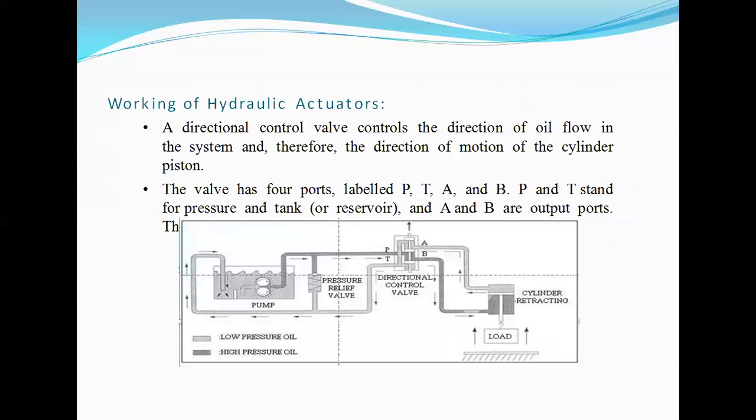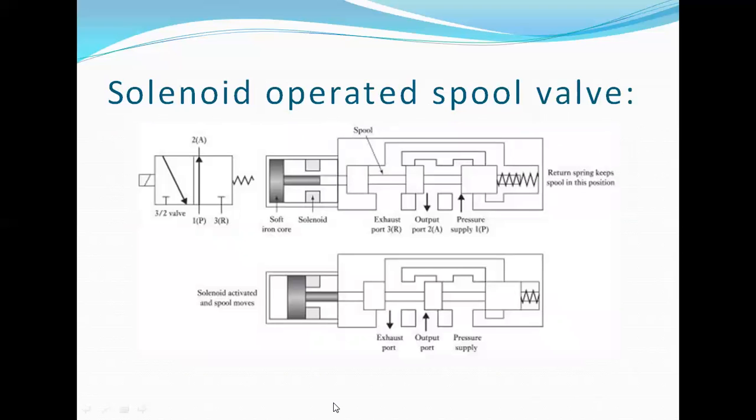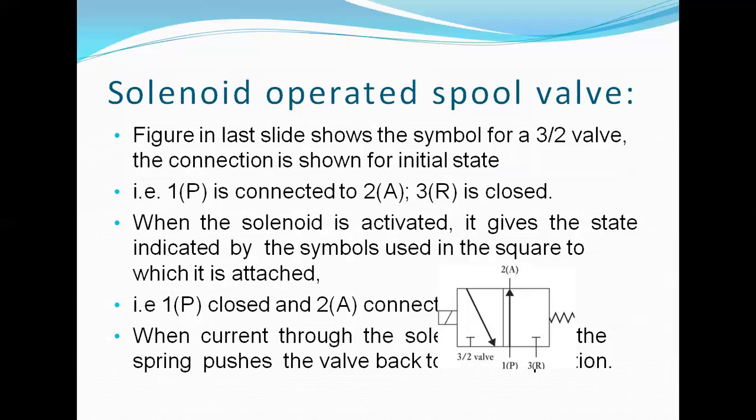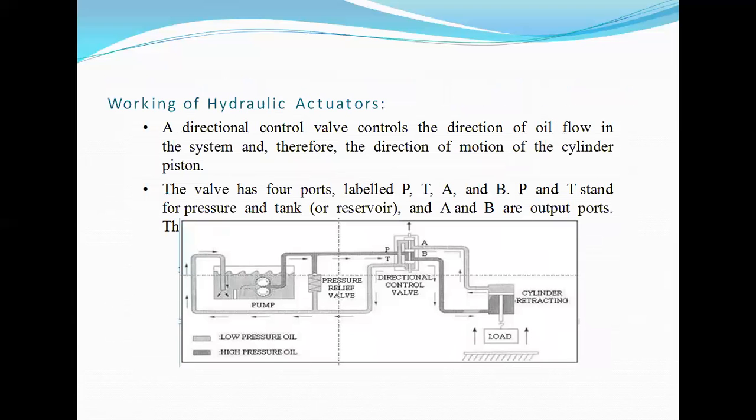In hydraulic actuators also, the same valves will be utilized, but there is one difference. With pressurized air, that is pneumatic, the air is released directly at the return stroke from the output to the exhaust. But in the case of a hydraulic source, this draining has to exist. The drained fluid is returned back to the oil reservoir, and that oil reservoir is again pumped to the first input condition. So pressure supply in the sense of pressurized fluid supply in the case of hydraulic, and pressurized air in the case of pneumatic. Such a condition. So here also the same description applies in the case of this hydraulic system.